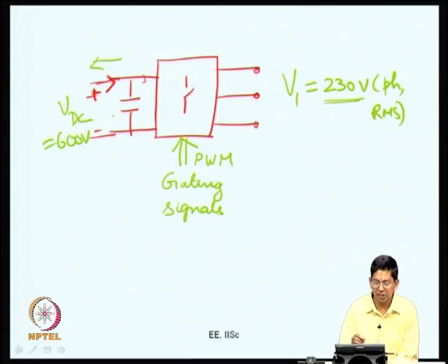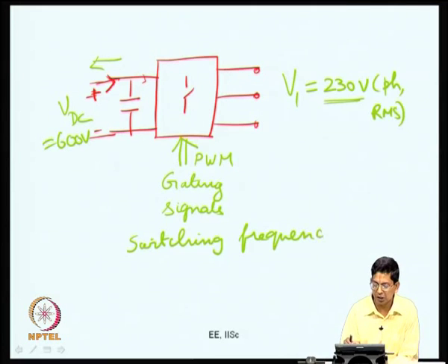So, one of the constraints here is about the switching frequency, how fast you can switch an inverter now. Switching frequency has some relationship with the power level at which you are operating. So far, we have been dealing with only ideal switches, but remember, switches have non-idealities. Ideal switches have no dissipation, whereas non-ideal switches have dissipation. What are those dissipations? One is conduction loss. Ideal switch has no forward drop, whereas a real switch has certain forward drop and therefore certain amount of conduction loss. And not only that, an ideal switch turns on and turns off in no time, instantaneous switching transitions, whereas real switches take a finite amount of time to turn on and turn off.